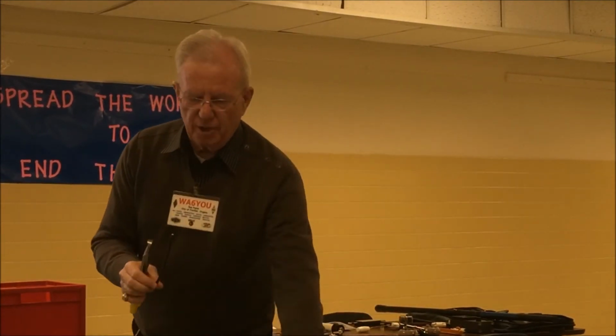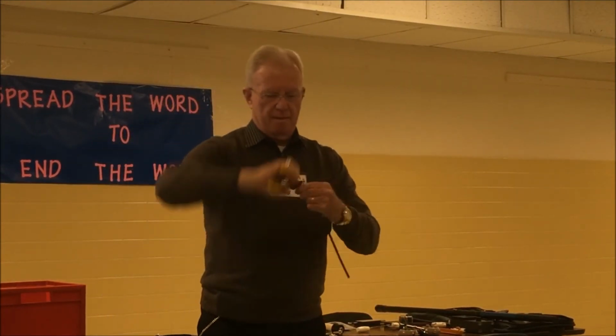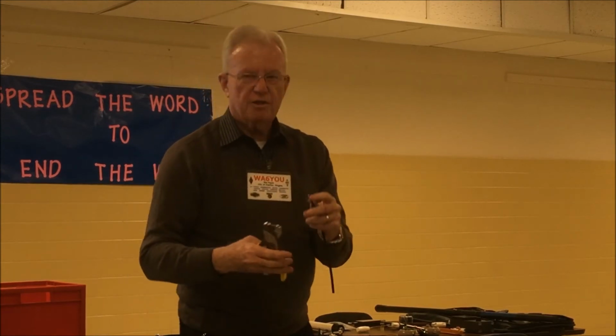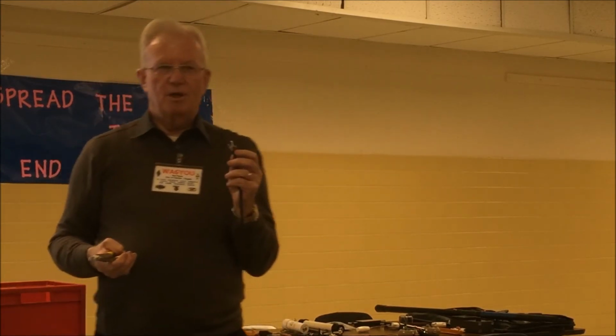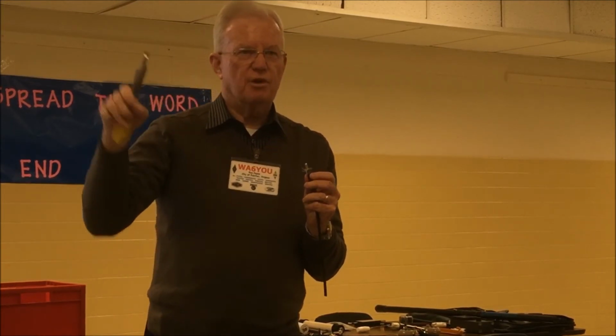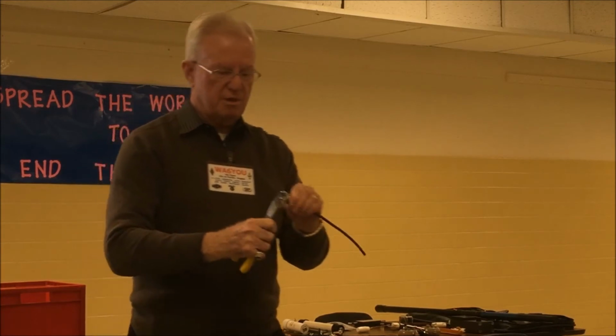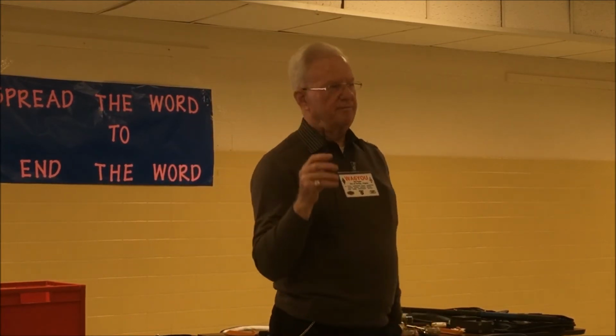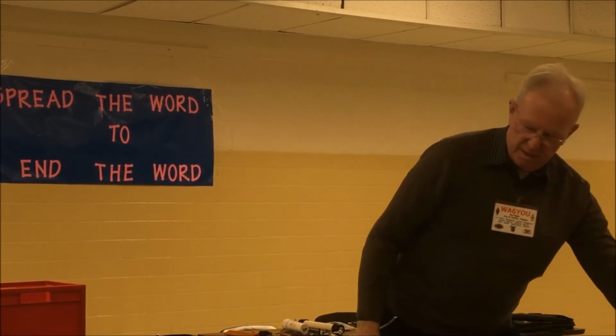This is LMR 240, double shielded. And make sure when you buy LMR 240 that you buy the LMR 240-UF for Ultraflex, because if you don't, guess what you're going to get in the mail? You're going to get a solid center conductor, and boy, you're going to be upset. Does this require special connectors? Yeah, of course. But I have all the crimp tools for all these, so I'll just pass these around.